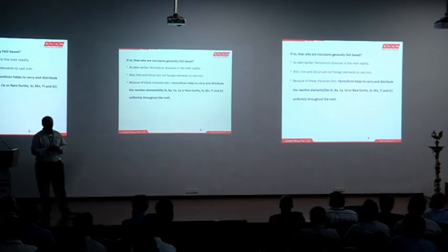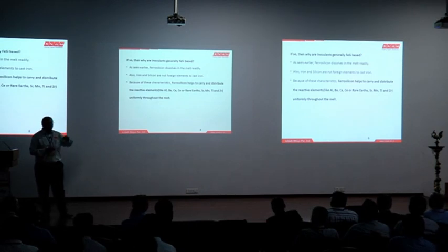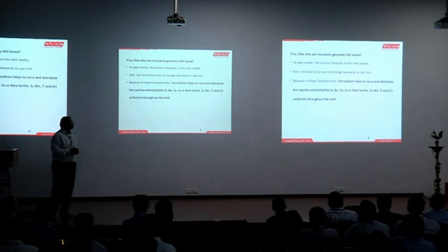So we need a carrier inoculant, or we need a carrier system which can take along the inoculating elements or special elements we tend to add, or want to add, to get the desired properties. So ferrosilicon melts at around 1220 degrees Celsius, and we add all these special elements to this ferrosilicon, and then we use ferrosilicon as a carrier material into the cast iron liquid metal.